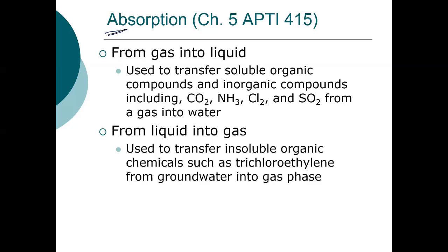Now we're looking at gas-liquid transfer. So we're looking at transfer from a gas to a liquid. Typically, we're looking there at soluble organic compounds. For example, CO2. We can absorb CO2 from a gas stream into water. Ammonia, chlorine, we typically do that in water treatment, for instance, or wastewater treatment. SO2, so we use it for desulfurization of the gas stream and removal of SO2.